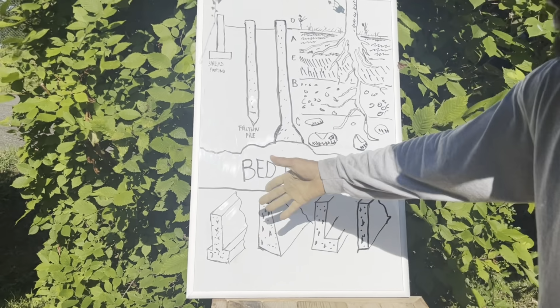And what the footing does, the footing basically lightens the load on your soil, because see how the footing is wide? The footing is taking all the load and spreading it out, giving you more surface area, which is going to put a lighter load on your soil, so you don't tip the scales with your soil.